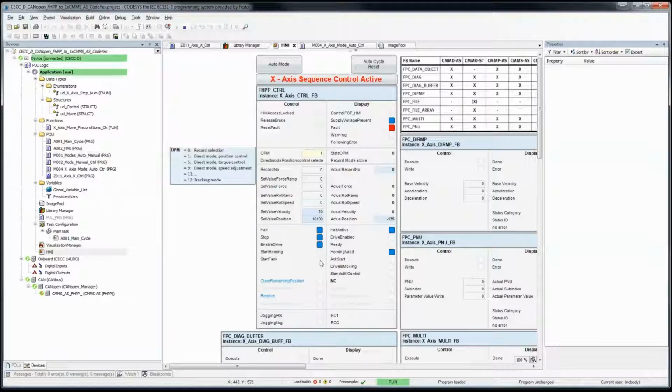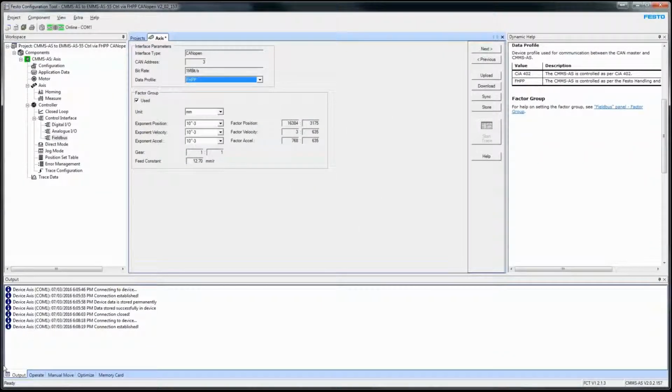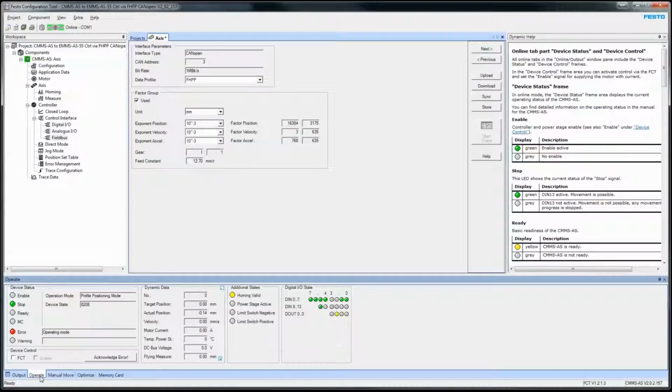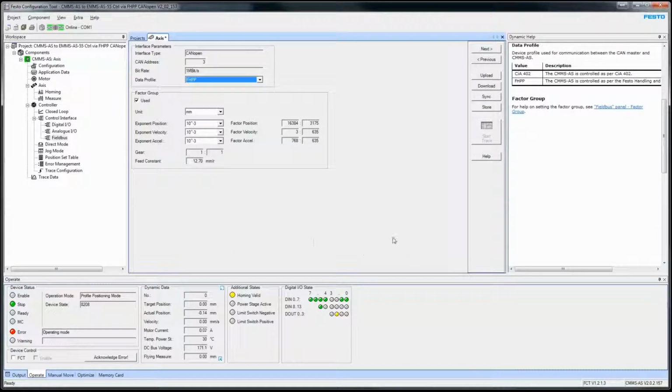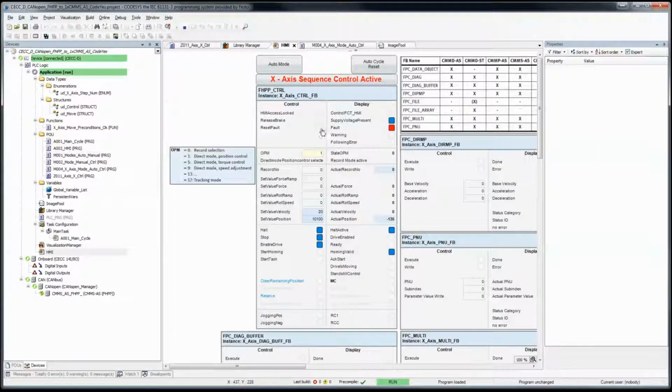And how do I execute a move? I turn on the start task. It doesn't work because I have a fault. The fault itself is operating mode. Oh, that's because of what I did earlier. So clear the fault. Now I'm back into mode of running, and I'll hit the start task. It's executed and it's moved.